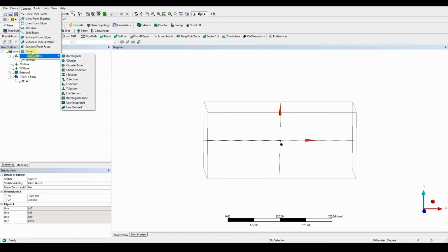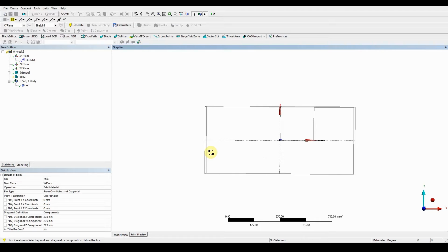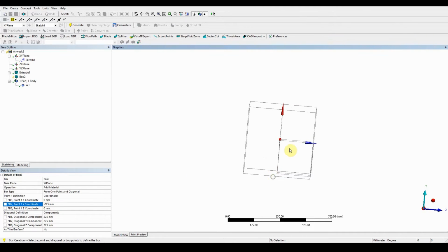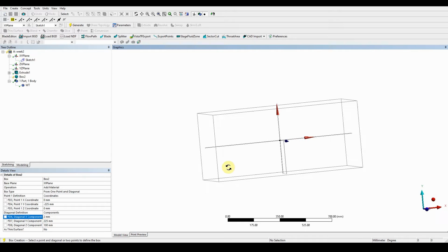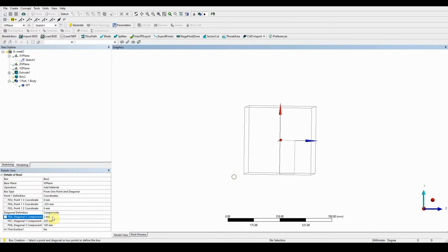So create primitive box section. Now we know it needs to be 225, but what we're going to do is we're going to put minus 225 there, so it goes behind. Now obviously we don't want it all the way, so let's say it's going to have a Z of 100. Yep, that should be fine, and a thickness of say 2 millimeters. And that's going to be a nice plate that sits in the middle, that's going to be affected. Now because it's 100, we just want to make that one minus 50 so it sits in the middle.